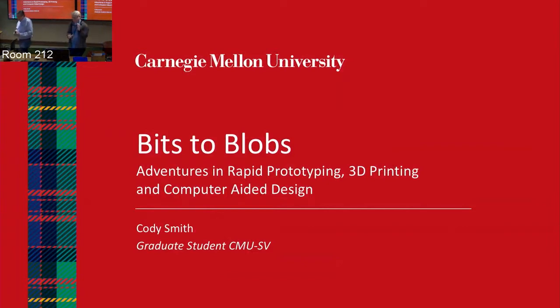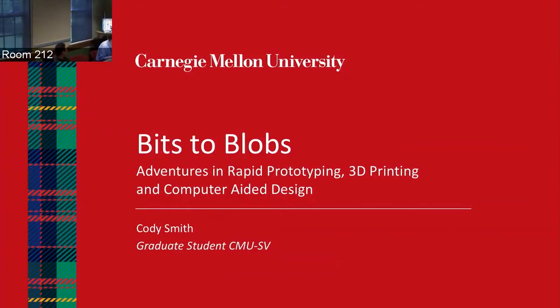Thank you, Bob. I have a 3D part we're going to print in this little lecture. It's going to be this part right here. I specifically designed this to print sort of just in time, so I'm going to go ahead and start that off before we get going. The way this works is, you'll have a design. You'll save it to an SD card. You'll put that in the printer. Go to the main menu. Print, reads the card. There's the part file. It's going to tell you how long it's going to take, and you're off to the races. So that part is easy.